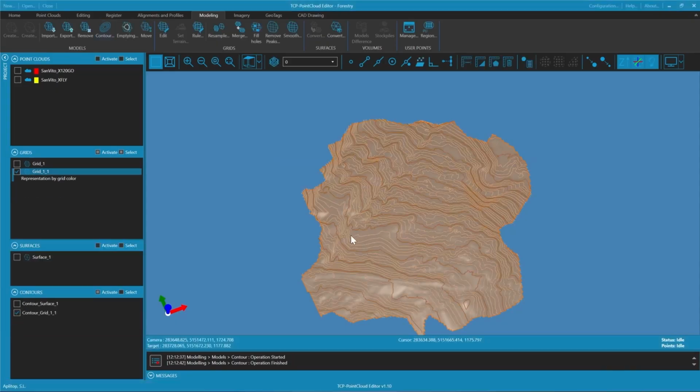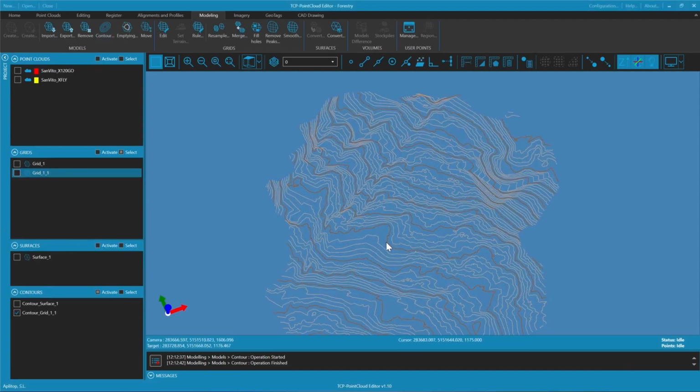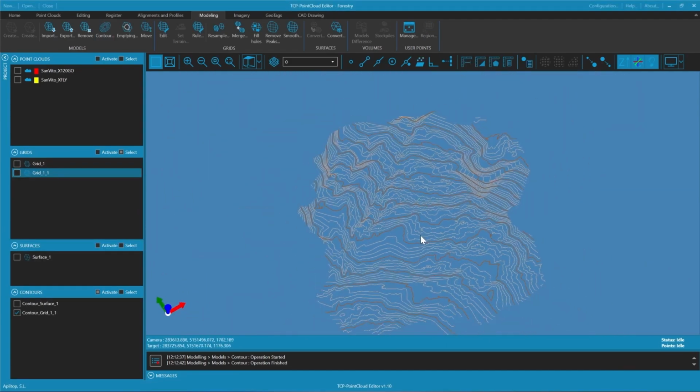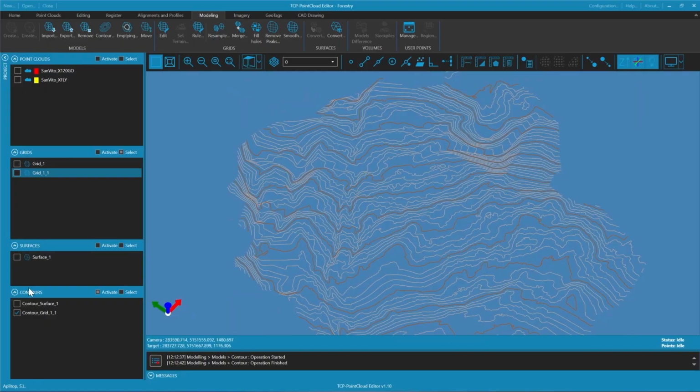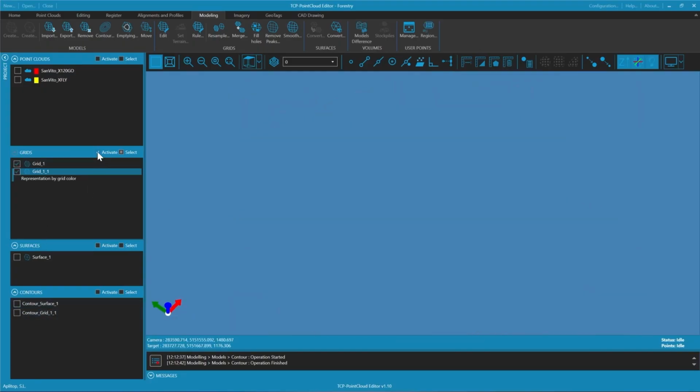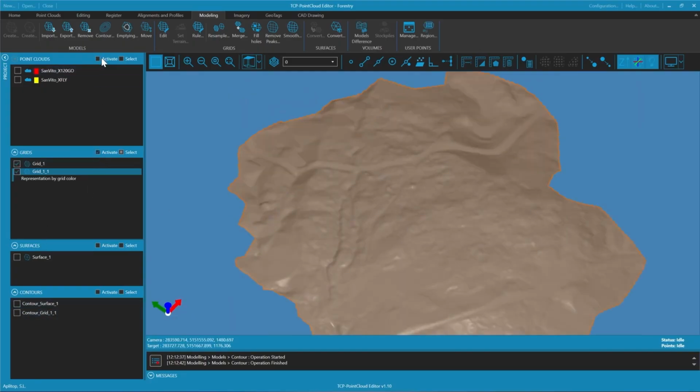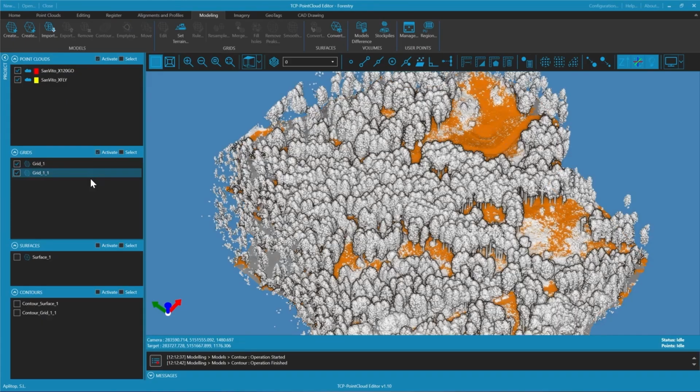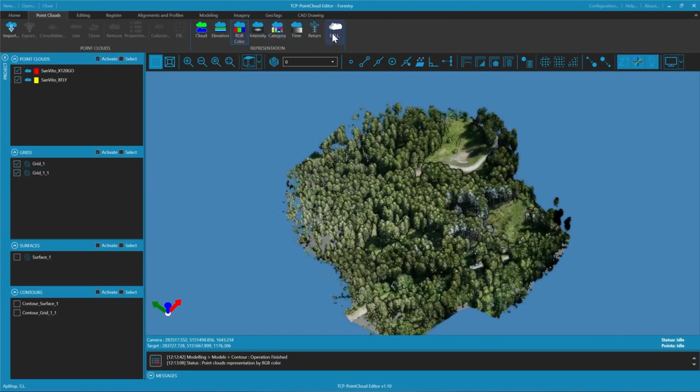Of course, this can be a destructive process and you could be afraid of losing the real information from doing that. How can we check that we have not applied too much smoothing? By making a profile. So we enable everything and we're going to set up a quick profile in the top view with a resolution of 5 centimeters.